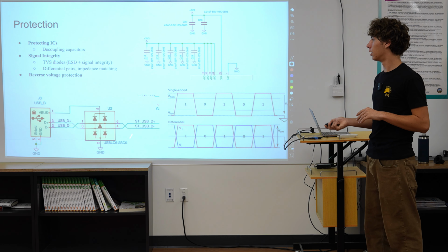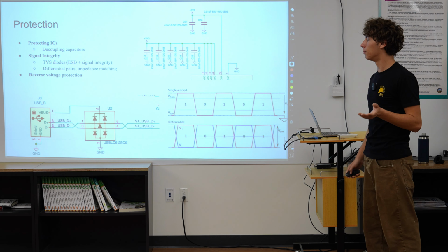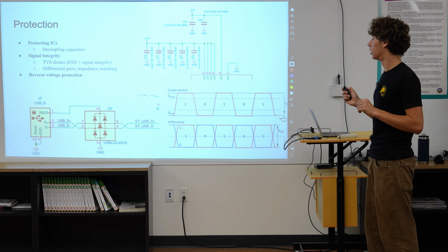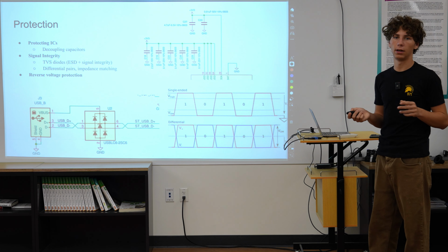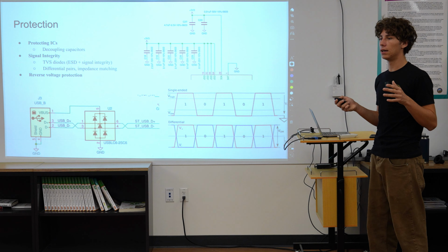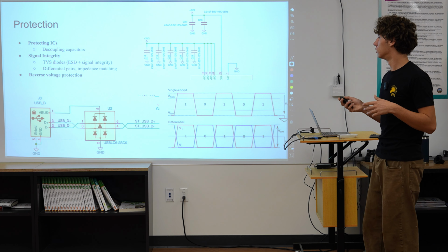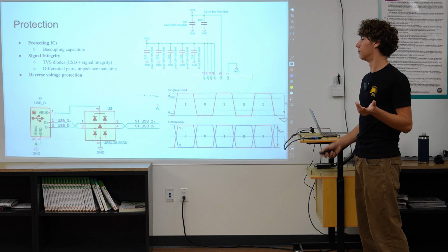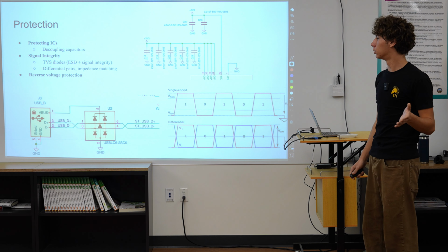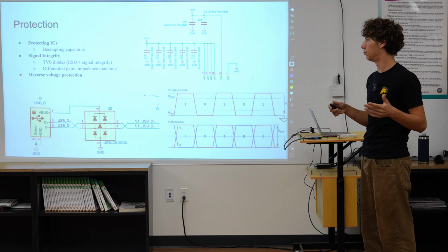So that's going to be this stuff right here. This does the same with spikes. And then we also use differential pairs instead of single-ended pairs. That kind of makes our signals more redundant, which is better because we've had signal integrity issues in the past with some of our signals. Basically, switching to differential pairs has solved basically all of that.